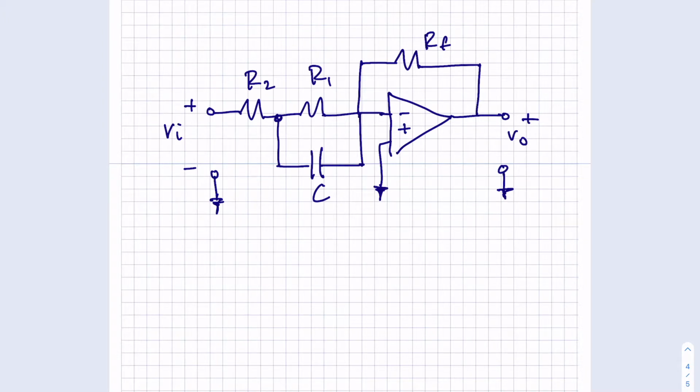So what that involves would be, instead of using the time domain, we're going to take the Laplace transform of VI and we would get capital VI. And we'll take the Laplace transform of the output, that would be capital V out. And resistors stay the same in the Laplace domain. And we talked about a capacitor: when you take the Laplace transform, you get 1 over CS for a capacitor element. All right, so this is our circuit in the Laplace domain.